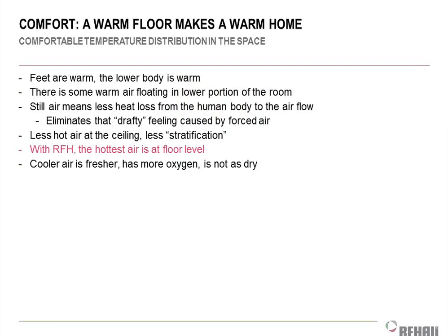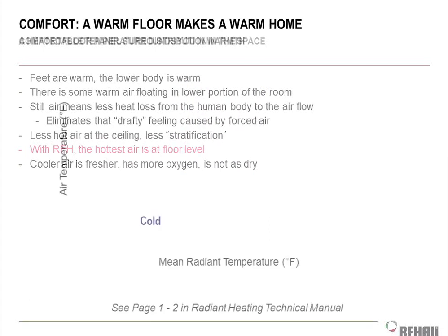So they're always complaining that it's cold, and they all got the electric space heaters under there, and the guys are always complaining it's hot, right? By the way, I've never seen an electric space heater on an office floor that had radiant heat, right? If they got radiant floor heat, nobody's using electric space heaters. So you're saving money, keeping a lower temperature set point, and actually keeping people warmer. It's kind of weird, but that's kind of how it works.